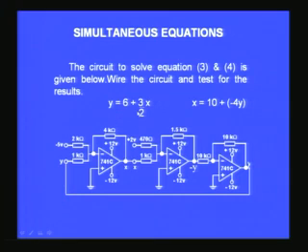So you can see here I have chosen some values of resistors, and I have a complete circuit here in front of us. It is very similar to what I already mentioned to you. For example, I have used the Vs, the reference voltage, to be minus 5 volts, and I have used a 2K resistor here, 4K resistor here in this first amplifier. So if I have only this input, what is the gain of this? The gain of this is 4 kilo ohms divided by 2 kilo ohm with a negative sign because I am applying to the inverting input. So minus 4 by 2, that is minus 2 is the gain, and that should be multiplying the input which is minus 5 volts. So it will become plus 10 volts at the output if I have only this first signal.